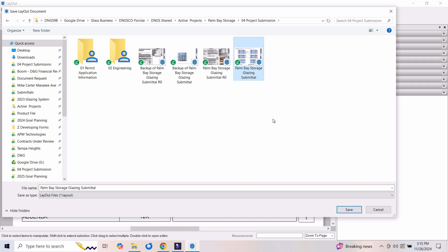The thing to be aware of when you create a copy or save this as R1 is that both files, the original and the new one, have all of the same media references internally. Because the Layout files are referencing media files, if the media files change, you could propagate those changes into the Layout document when you open it and update the links to media files.